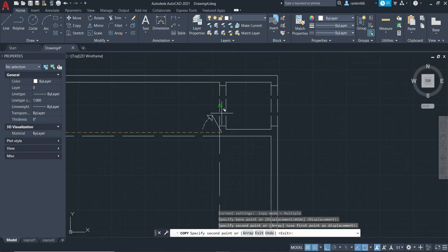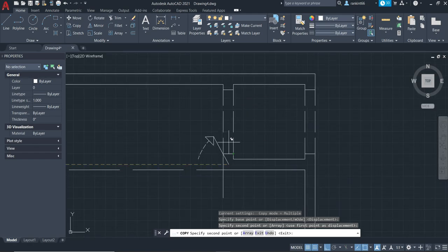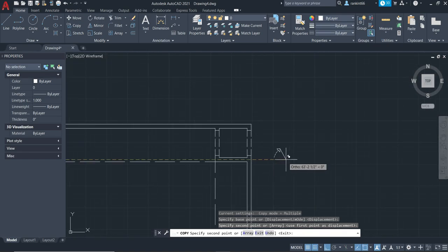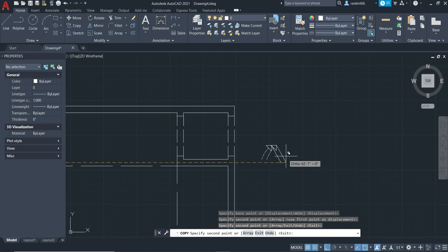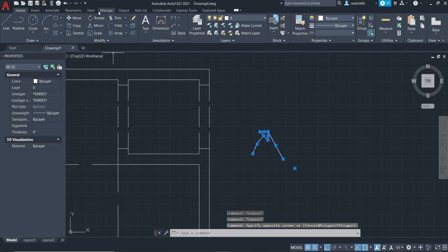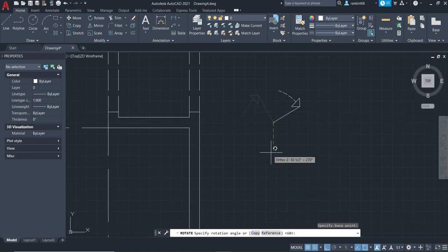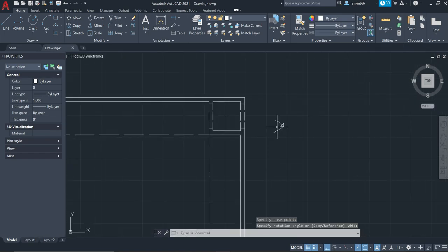The last ones are these doors, and they all open towards the back, and these are double doors. So they follow the same 3-foot width, and they want to have that same proportions to it. So I'm just going to go ahead and drop a copy of that same door to the side here and hit escape. I'm going to select it, and I'm going to rotate it. So I'm going to go up and find the rotate tool up here. So click a base point, and because I have this tool turned on, I can rotate it. I want to make sure that it's going perpendicular against this midpoint here. So there, and click, and I've dropped it.